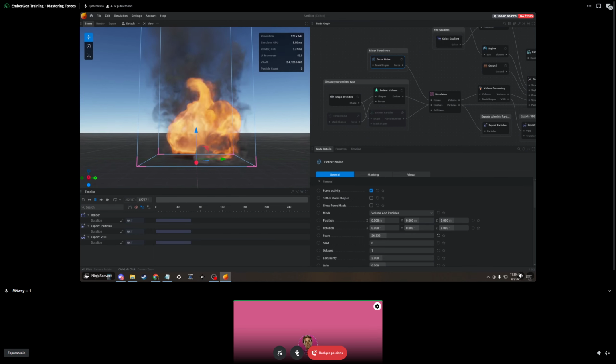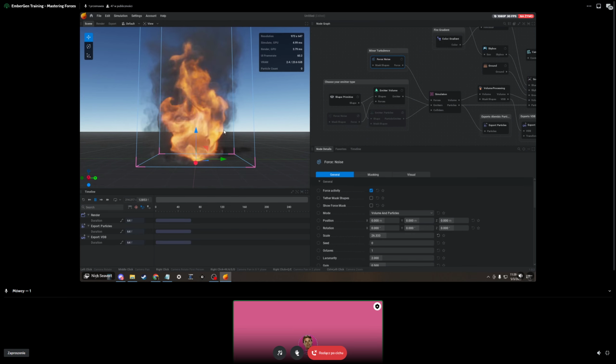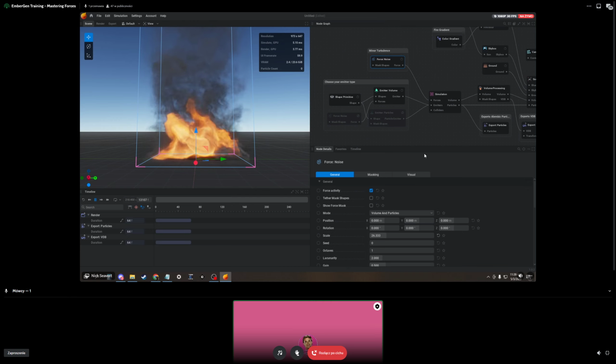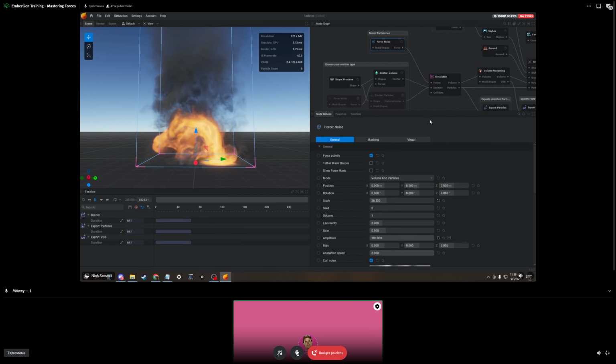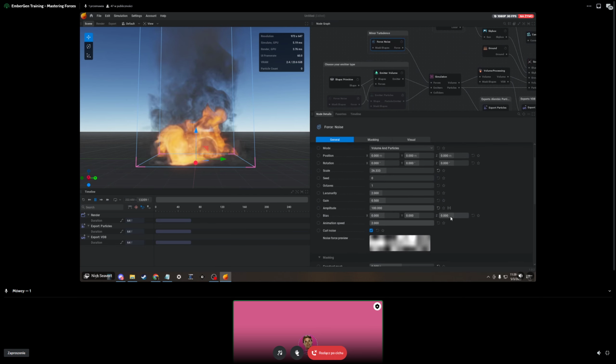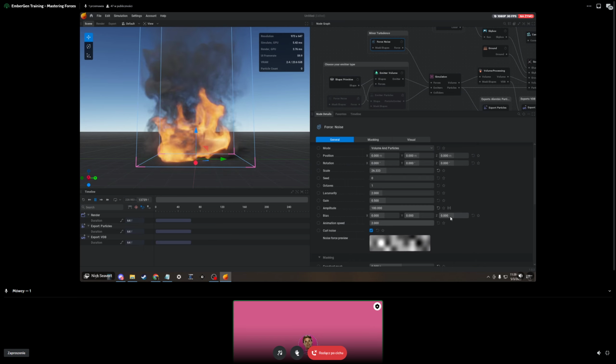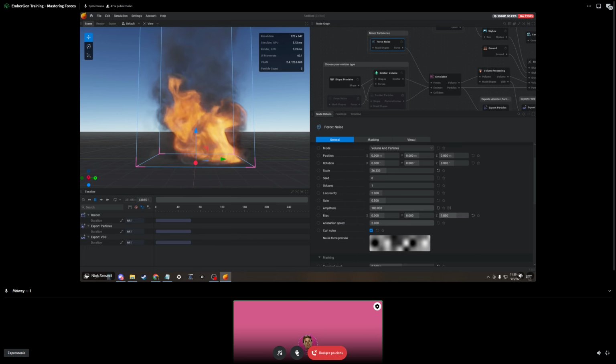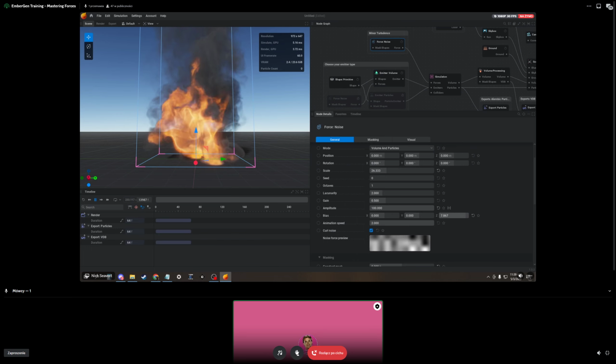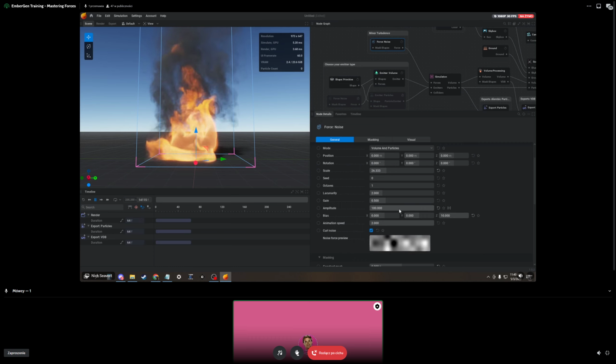One of the weird things is that it's chaotic in full 3D, in every single axis. One thing we can do to circumvent that, if we want a force of chaos in a certain direction but don't want to use a line force because we want a lot of this chaos, is you can do a bias. So we can say, hey, I want this to be biased in the Z axis.